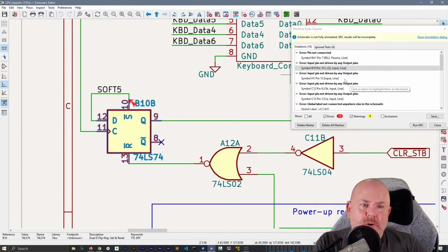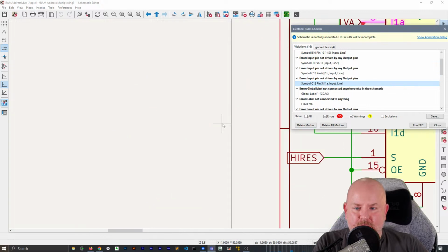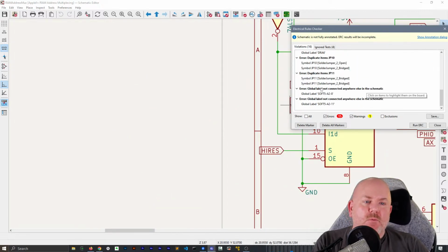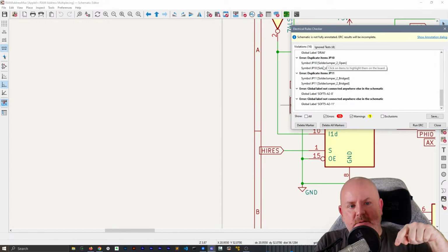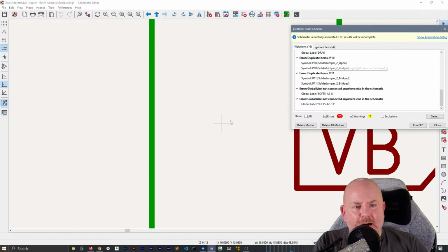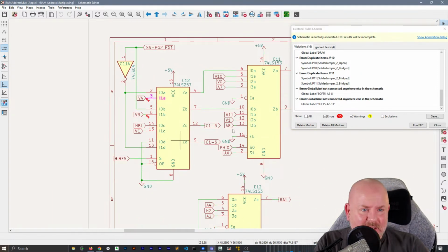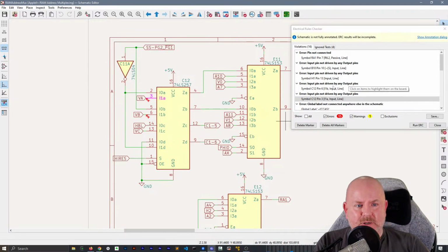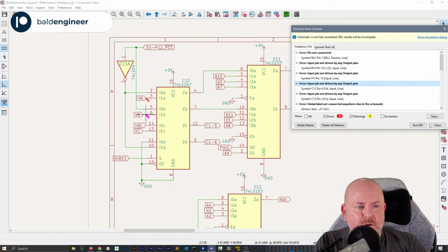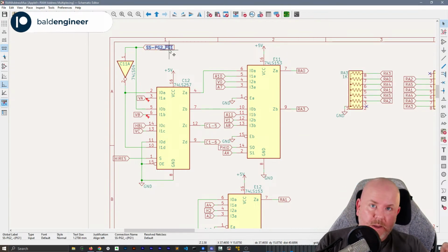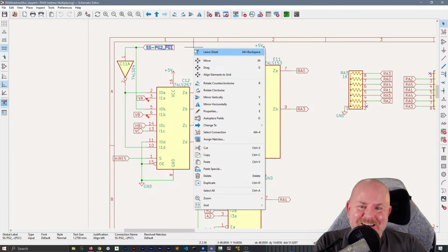I think we're going to be at a point where, yeah, okay. And then these I knew about. Let's see, what's this complaining about? Yeah, okay. Basically where we're at, there's a couple of duplicates, which we need to look at the original schematic to determine what they're supposed to be. There's that flip-flop that is not connected right. I think that's a mistake. And then there's some issues with these input and output pins, but that's because the labels are messed up. So what we're going to work on tonight is converting these global labels to hierarchy sheet labels and then connecting